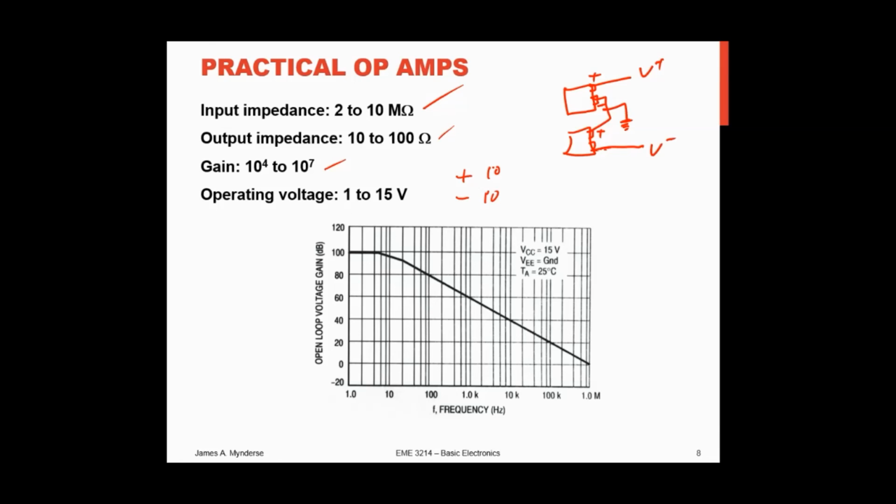That's the easiest way to make a power supply for these op-amps, just a couple 9-volt batteries, okay? So it's not a disaster. Frequency response, I don't know what exact op-amp this is for, but basically, you get much above, looks like about 10 hertz, the response starts to fall off. So this one isn't very fast, but you can get faster ones.